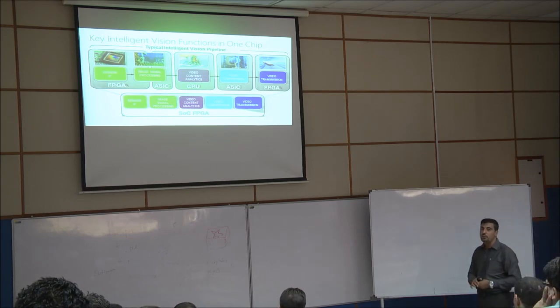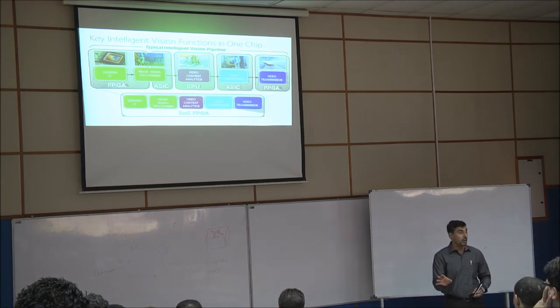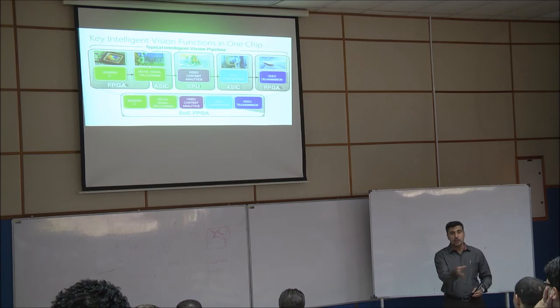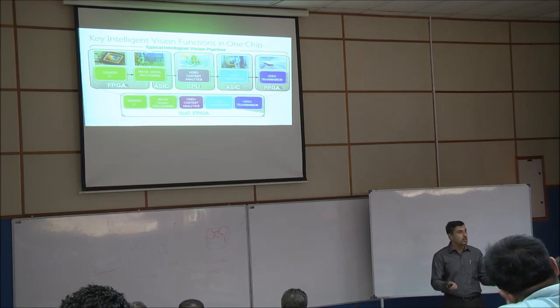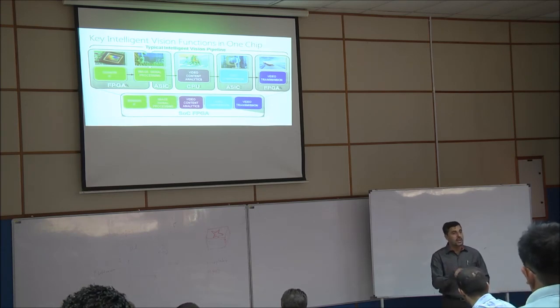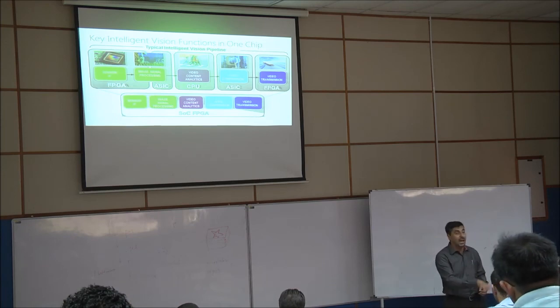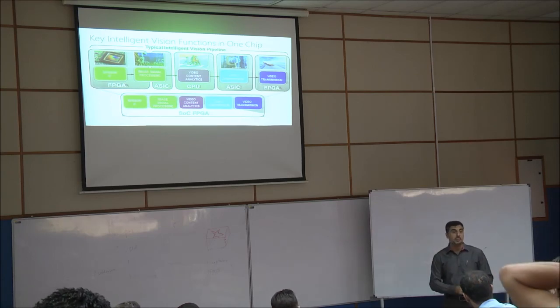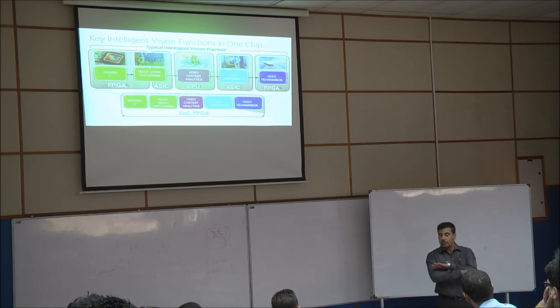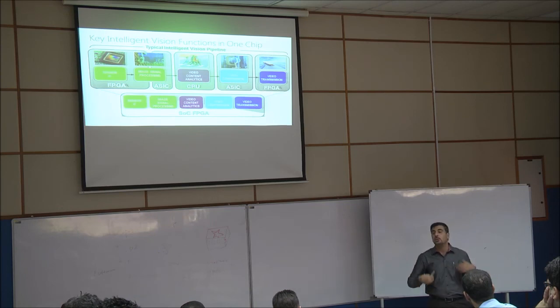Because the only technology that gives you true parallelism is FPGA, reconfigurable. One of them, FPGA. If I ask you whether a microprocessor like an i7 can give you true parallelism, maybe you say, oh yes, because it has 8 CPUs, so it's true parallelism. No. There is still dependency because of the shared memory and distributed memory, and buses as well, right? So there is no 100% parallelism, correct? When I'm talking about true parallelism, that means inside an FPGA we can build different engines totally independent of the others. Clear? That means the resources are all cut. They are not sharing the resources. This is what we call true parallelism.